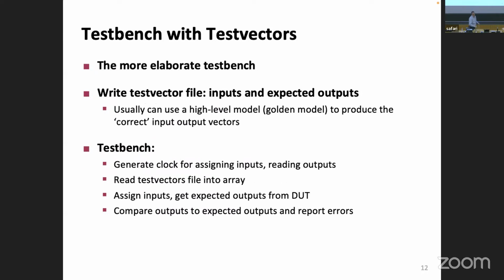So here is what we want to do, a little bit more elaborate test bench. We want to have some test vector files that contain the stimuli and maybe the expected results at the same time, read them in, apply them at the right time, and generate all the rest. I don't want to say like, wait 10, do this, do that. I want to have a sequential circuit.